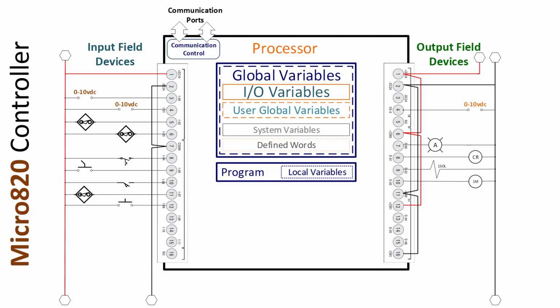They are just memory locations that you, or the manufacturer, have created a name for and defined: pointers, variables, tags, whatever you want to call these memory locations. All those names are usable, and we will use those interchangeably throughout this course. Specifically, Micro 800 calls them variables, but you could also call them pointers because they point to a memory location. Remember, memory locations are numerical, or you can call them tags or tag names. Besides a name, you have to define them with a data type.